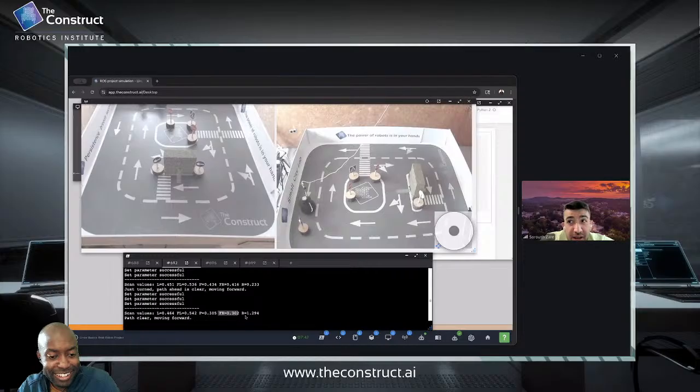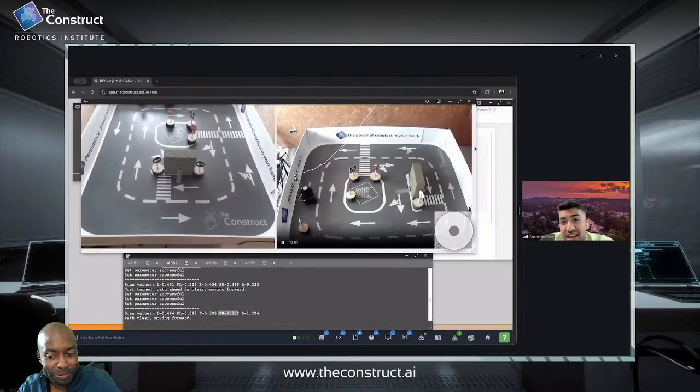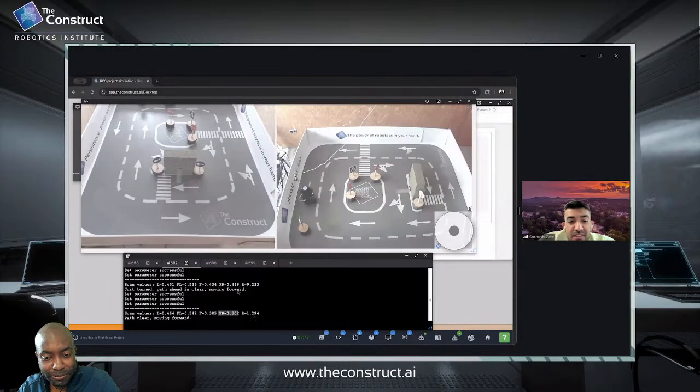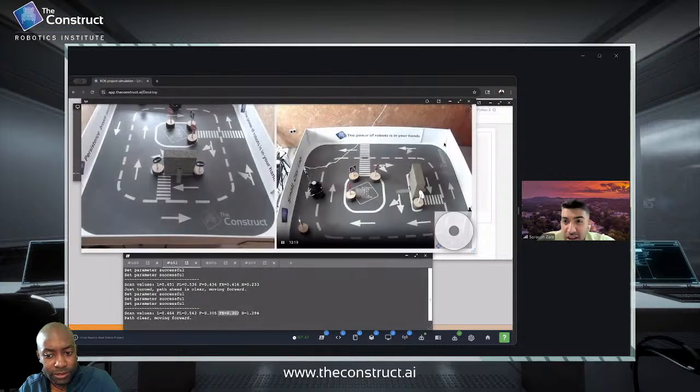But we should also care that it does not get stuck, because if it was a clear path and it sees that the whole path is not clear, it's going to go back. So we should avoid that and have some memory to not go back, just remember the last task was, for example, forward, so avoid going backward. Because here also with some speeds at the corners, I figured out that if we set the angular velocity high, it just goes around itself and twists all over.